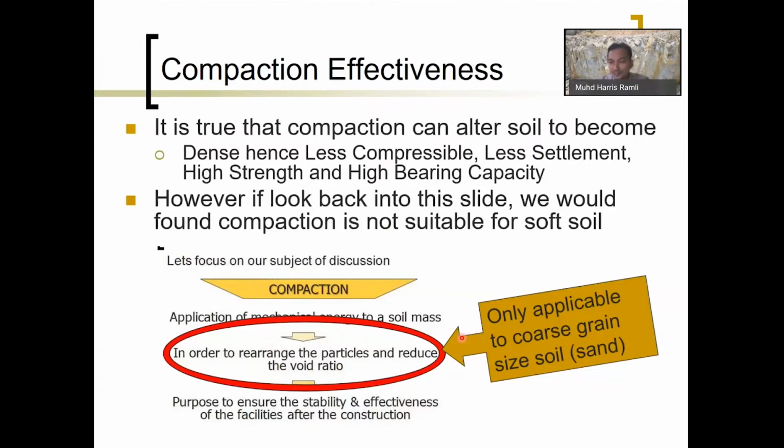Okay, take a sample of the soil there. You can actually know the percent of clay as well as the percent of sand. And in fact, with JKR requirements, they also have requirements on what is the highest value or the lowest value that is suitable for compaction.